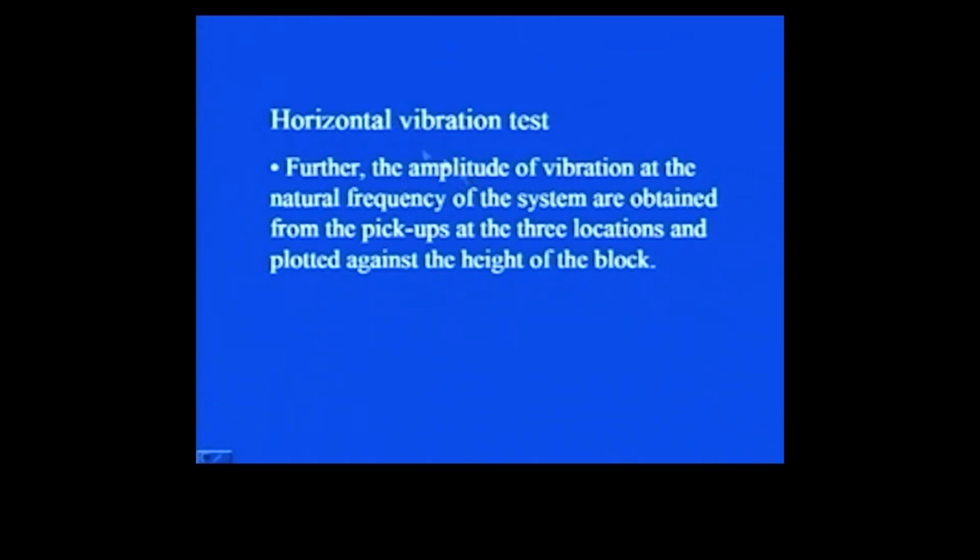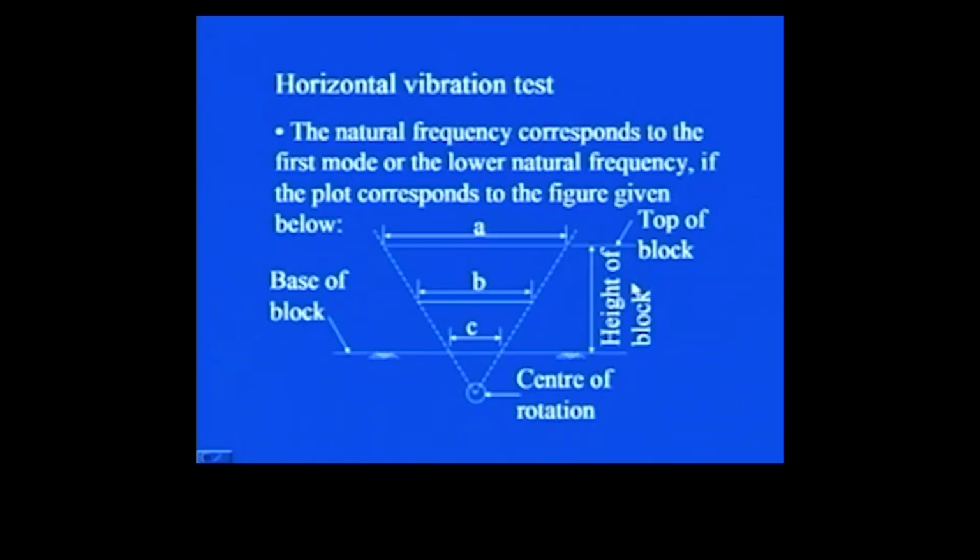Once you know the natural frequency, you can note down the amplitude of vibration. You have mounted the acceleration pickups at 3 locations, that is top, middle and bottom, so that you can plot against the height of the block.